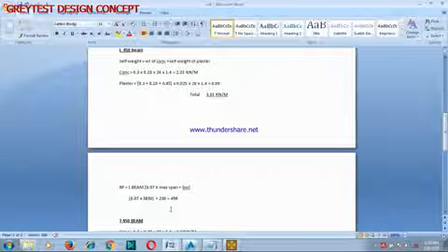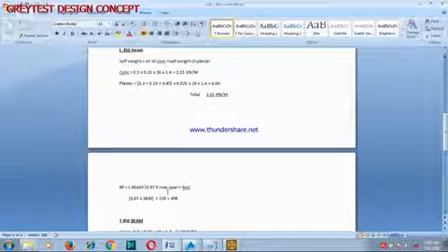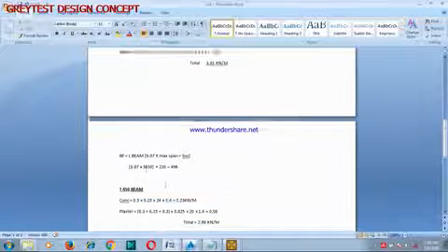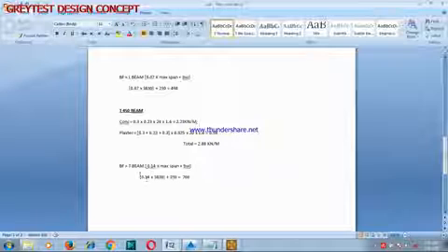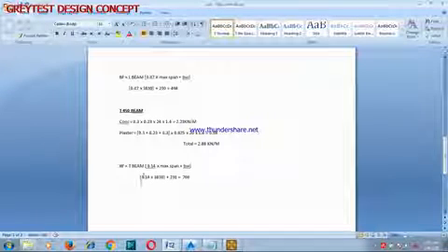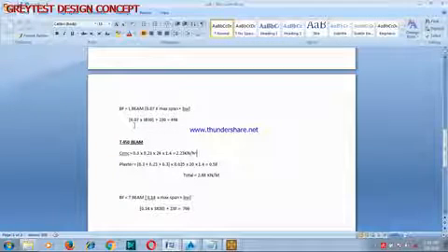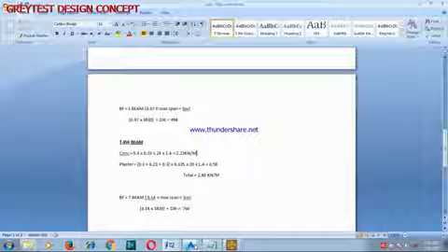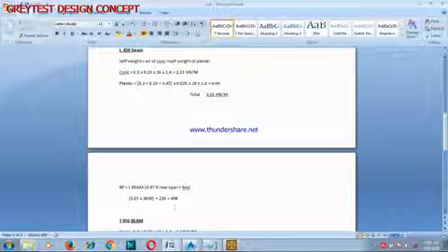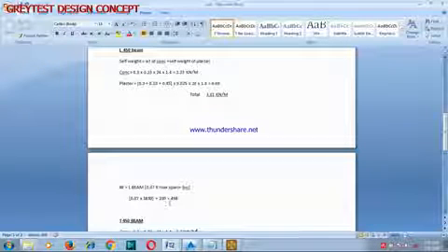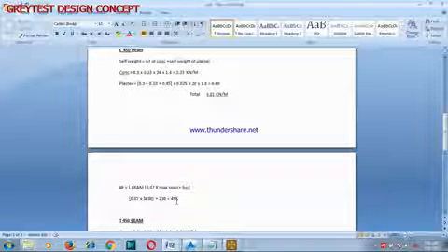That will give you your BF. That's when you are dealing with an L beam. On a T beam, the difference is going to be in this particular value. It is going to be 0.14 instead of 0.07. That is how to get your BF. So since our beam 1 is an L beam, our BF is going to be 498.